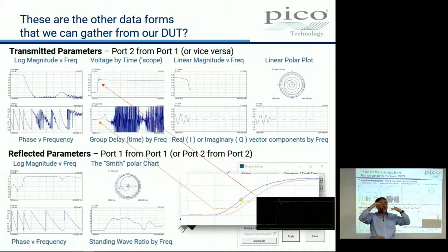Ouch, right? So it's very important in a communications channel, when you're having a modulated signal of any kind whatsoever, if different bits of the data are in different parts of the spectrum, you better have flat group delay. Because otherwise your data stream is going to get corrupted. I mean, 2 nanoseconds is huge in high-speed data, isn't it? Yeah? So different parts of the data in different parts. So group delay is really, really important to communications engineers, anybody that wants to keep the signal aligned.